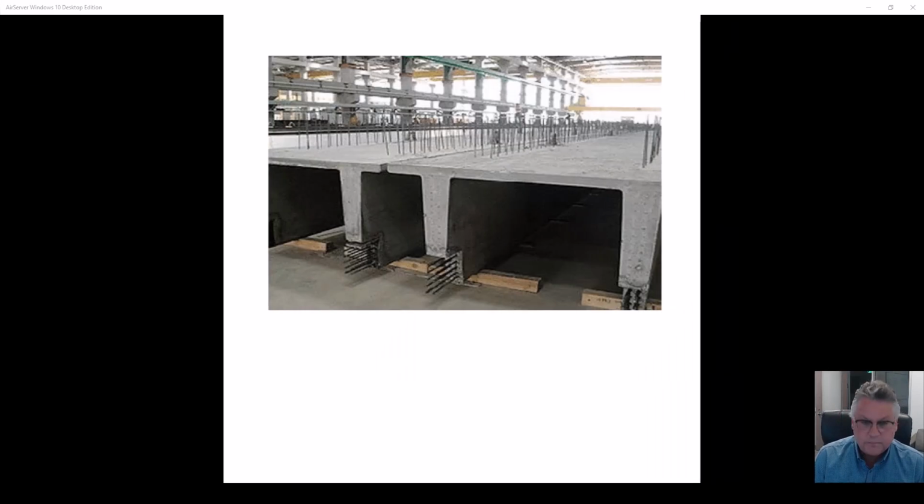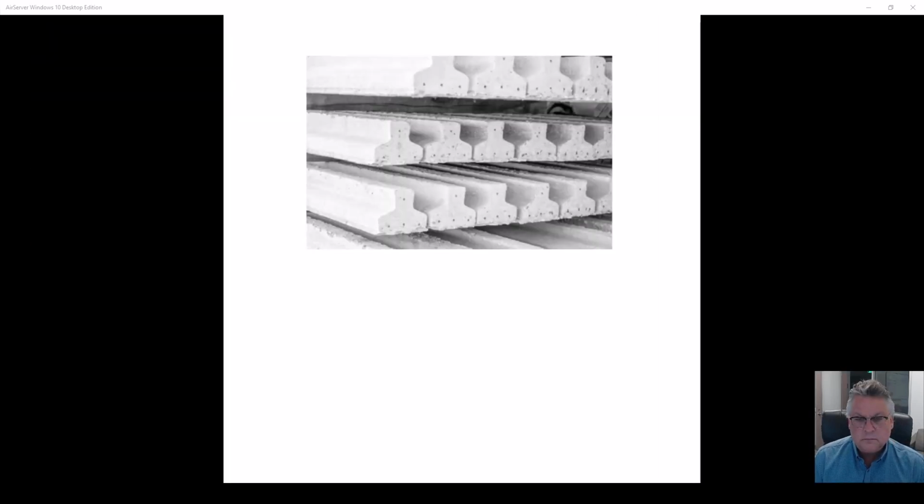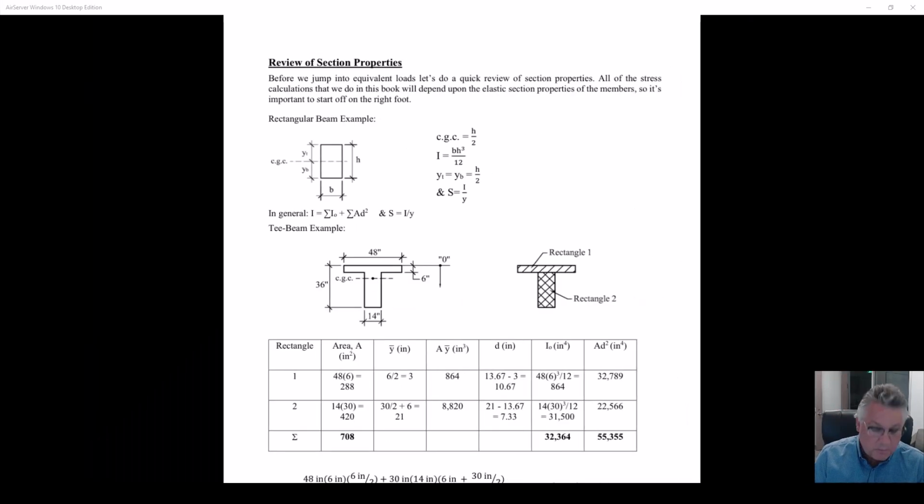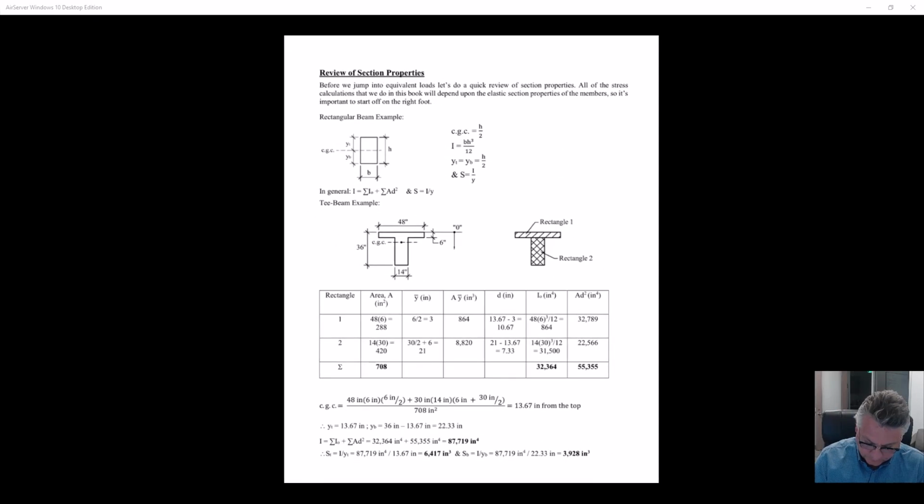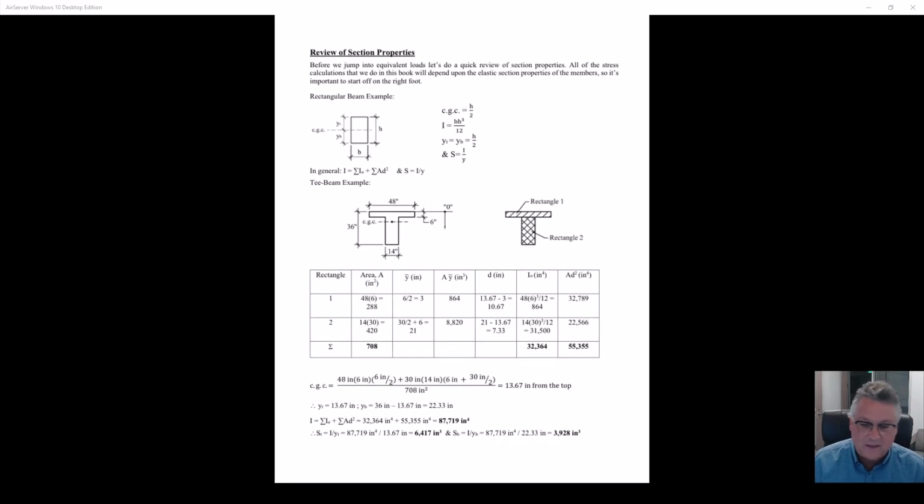So that's what precast, pre-tensioned members look like. They're basically built at the shop. They'll get shipped out. They'll just get placed on site. So it was really concrete's version of steel design. Steel was able to fabricate their members in a plant, ship them out, put it together quickly, and concrete wanted a version of doing that for speed. So we got precast from that. And then they post-tensioned their structures. Or pre-tensioned their structures. Pre-stressed.